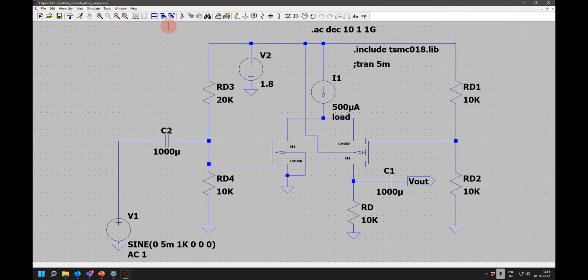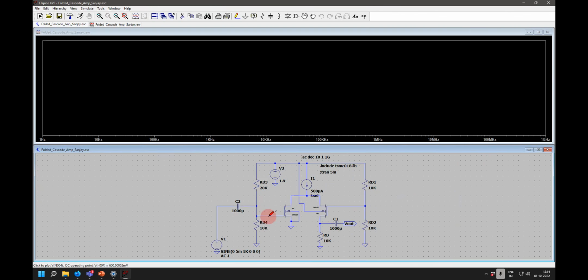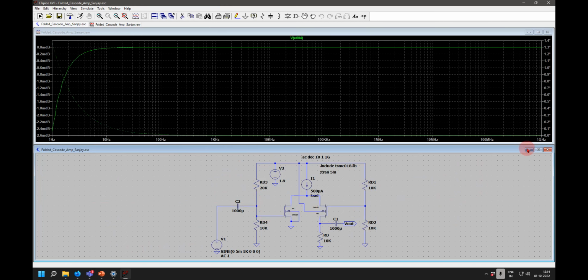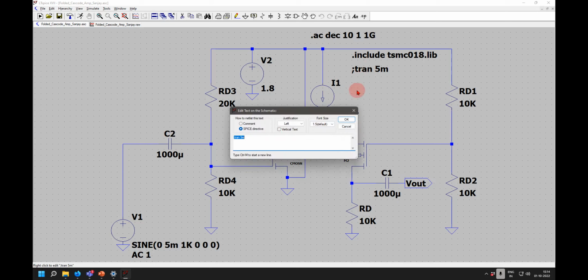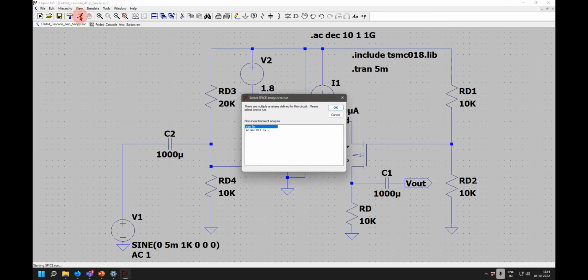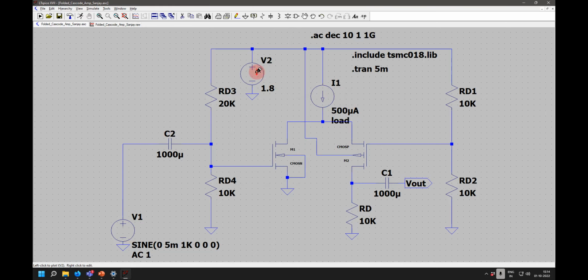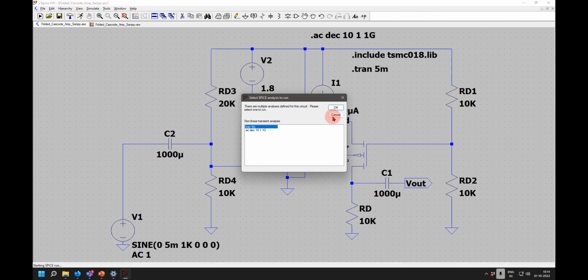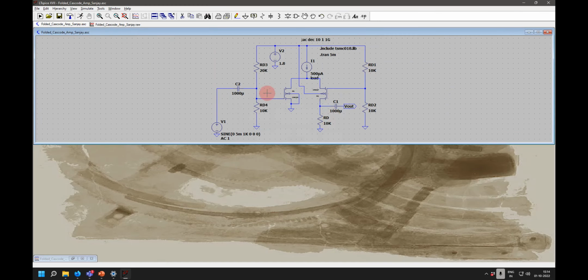Yeah, you can do a DC analysis, or you can do a transient analysis and plot the voltages available here. Actually, I just want to see the waveforms for the DC analysis. No, for a DC analysis, you have to sweep some DC voltage, right? So it is better to do a transient analysis and then plot those voltages. So transient analysis will give the DC operating conditions also. So this is the DC operating condition out here.